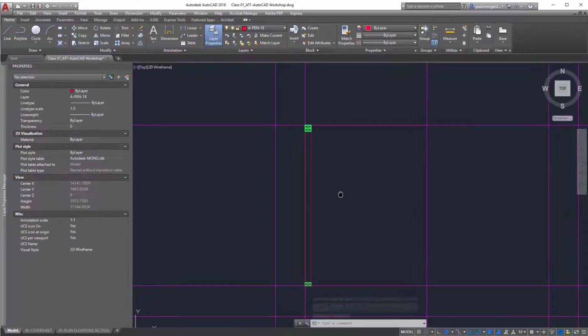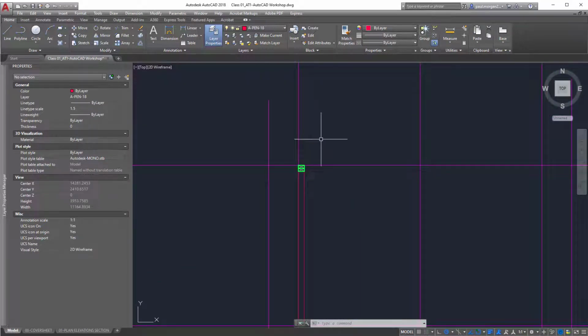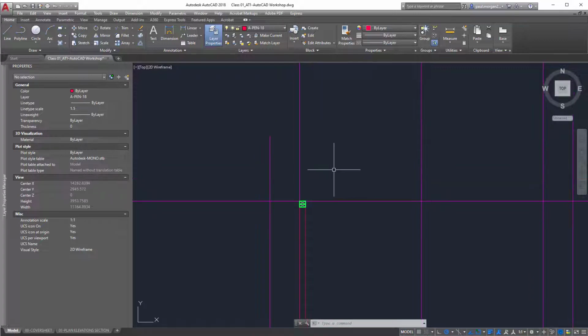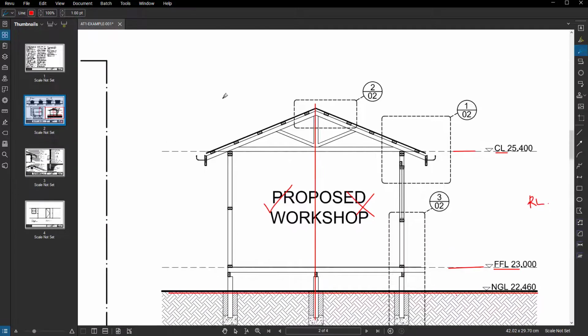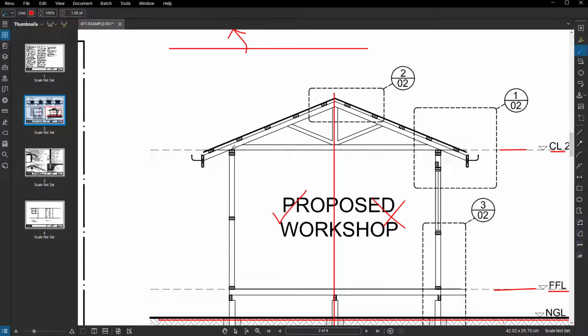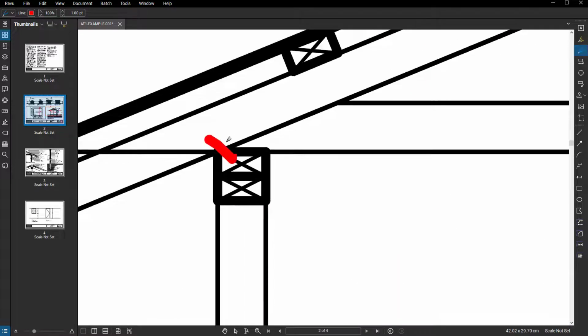All right. Next up is the roof truss. The easiest way to draw the roof truss is we're just going to draw a straight line, and then we're going to rotate this 22 degrees. That will give us just a random line here at some generic length we won't know. But the important position that we want to start this truss is this point here. It's the point where the truss meets the top of the stud wall, and where the bottom chord of the truss meets the top of the top plates.